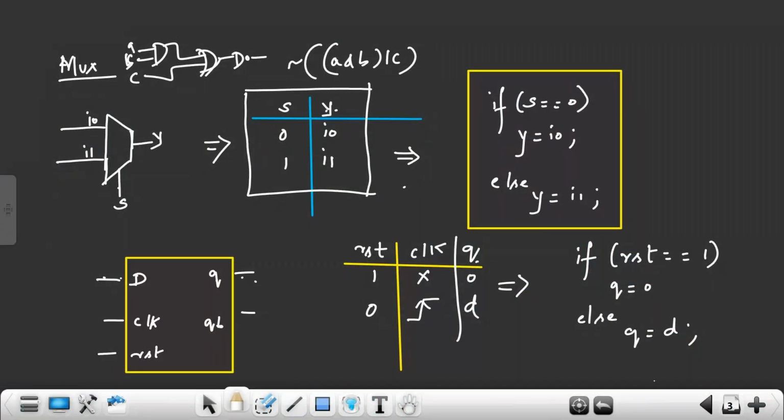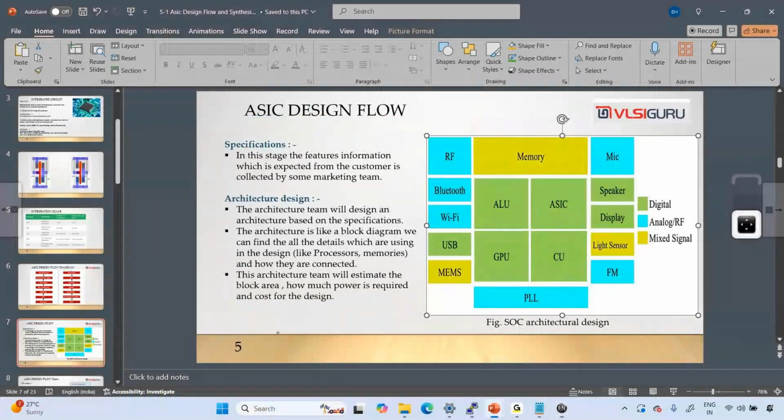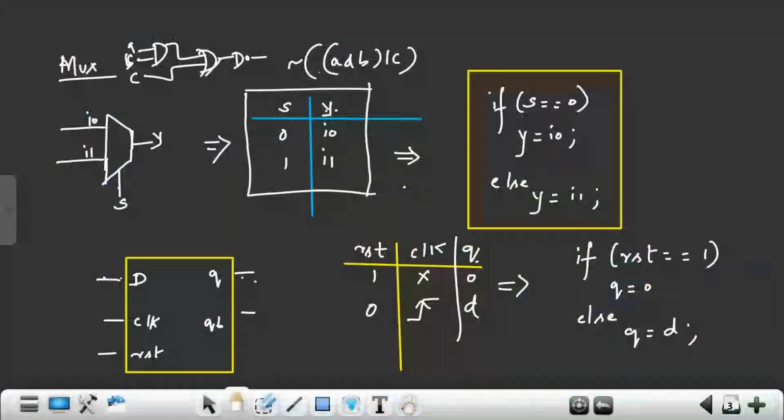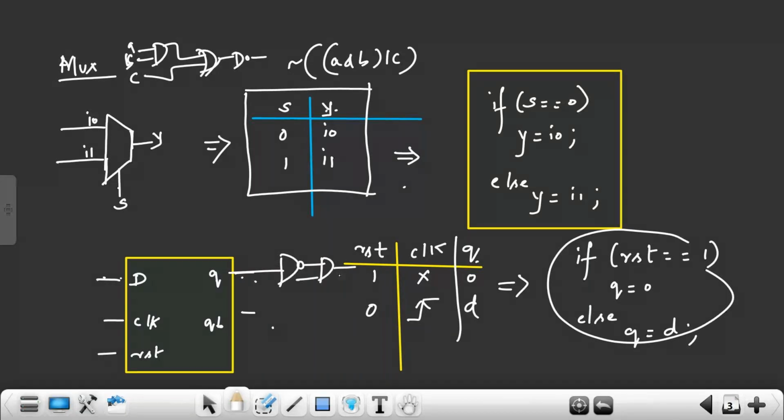So in between, one or two lines, we may also use data flow. Very simple lines. For example, I have written some behavioral circuit. For a D flip-flop, I have written the behavioral description, and the output Q is connecting to one NOT gate and it's connecting to one NAND gate. After writing this, I can mention what happens. This is Y. What is Y?